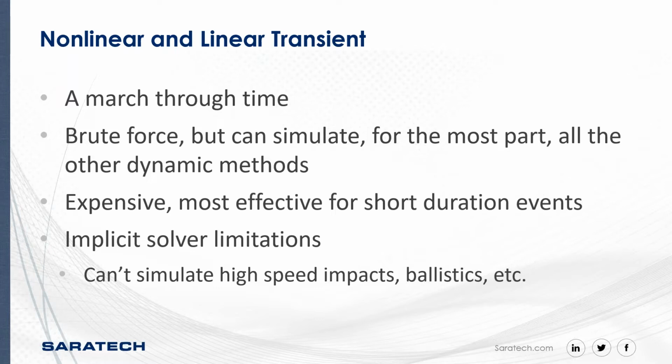The problem with this though is it's very expensive and it can take a very long time to solve for longer duration simulations, so it's best for short duration events. So imagine that we're taking like 1/10 of a second each increment, and we need to solve for an event that takes like 5 minutes. Not only do we have the iterations to converge for each increment, we also have every increment to go through, so that becomes a lot of solving.